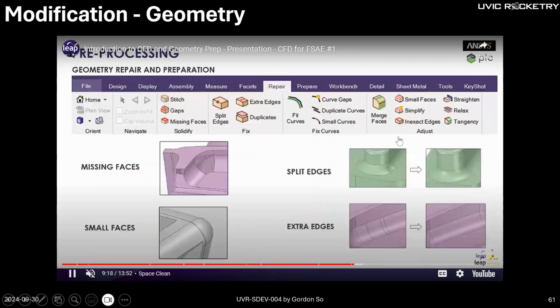And then some good features to modify: if you import it in ANSYS from SolidWorks, it's probably okay because it's actually solid. However, if you use surface-based exports, even like STEP files could have something like this, because maybe you sometimes miss a surface. Maybe you're doing surface modeling. So this would make, of course, zero geometry, because theoretically surfaces have no thickness.